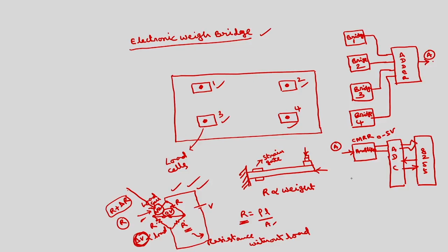So, we can write the program. The main contribution here is interfacing the A to D converter and how to start the conversion, how to end the conversion, and how to read the digital equivalent of this load. Okay. The program that we used for the temperature measurement is almost the same here also. So in a similar manner you can write the program of the electronic weighing machine, and if you want you can display the weight of that particular vehicle.